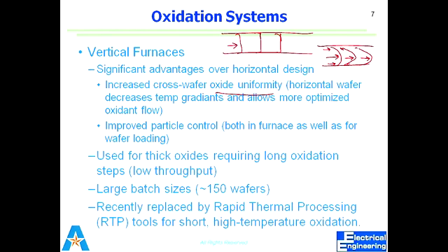In the case of vertical furnaces, you place every wafer in a specific slot. So when the wafer is heated, the temperature on the surface of the wafer is uniform. There should not be any non-uniformity in the oxide layer. You got the point: in the horizontal furnace the wafer is oriented this way, so heat needs to transfer from the lower end to the upper top.